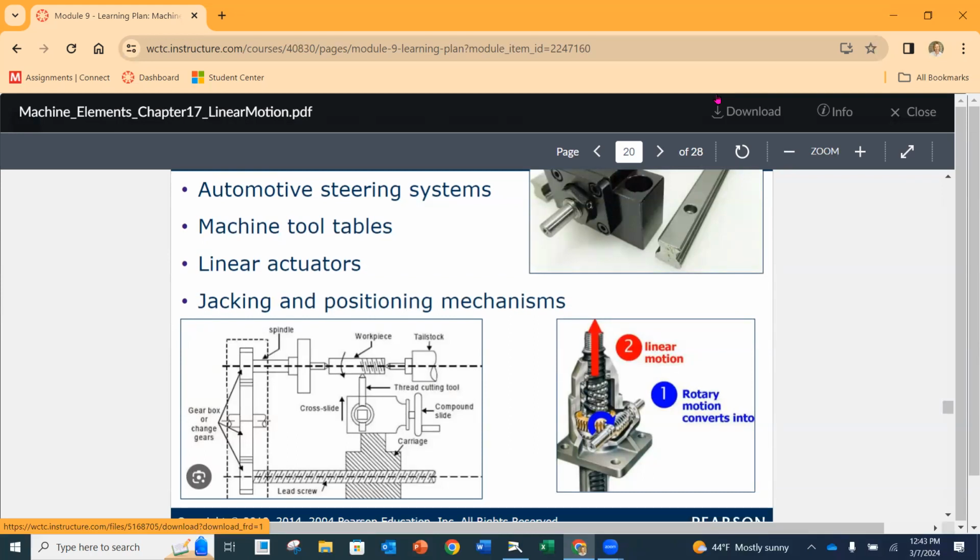Unisig. They made machine tools, and they use a lot of ball screws because of the speeds that they would have to move large loads for machine tools. And they offered that speed, the less friction, but then also the ability to dissipate heat, which was a big deal, right? So you get more speed, make cuts faster, so you can cut metal quicker.